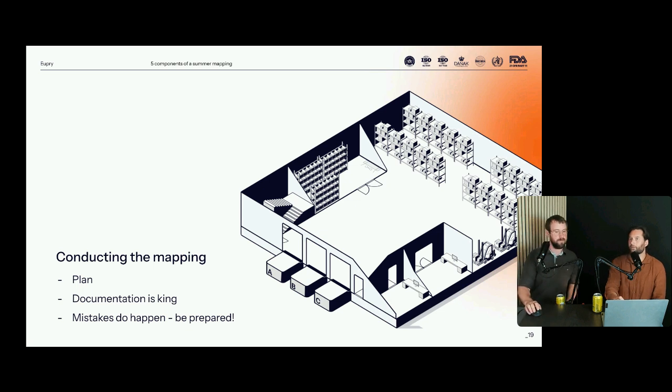Yeah. And here is also kind of where the real advantage of having real-time data comes into place, right? Because you are able to spot those mistakes almost immediately and act upon them without waiting until the end of the exercise, downloading from your old USB stick, and then seeing that something was going wrong, right? Absolutely. It's a matter of being quickly reactive to any kind of issues, and also a matter of data integrity, because you're able to act immediately and replace, for example, a malfunctioning sensor or logger in this case. Absolutely. And I think it's a really good point.